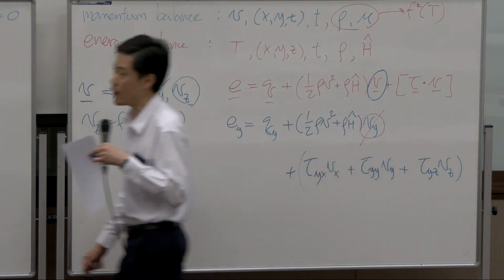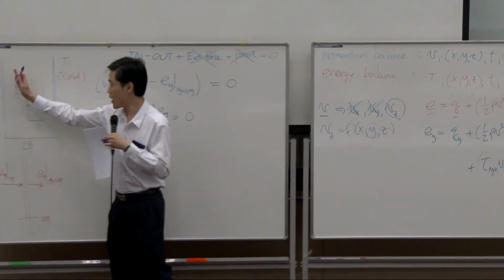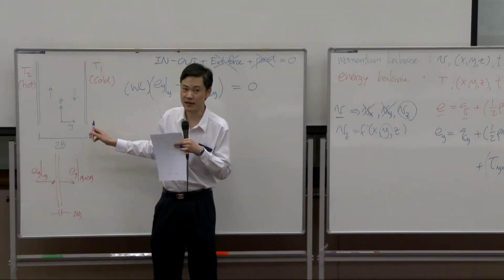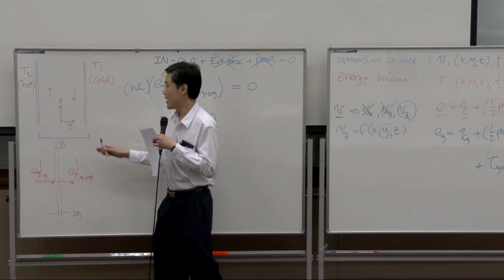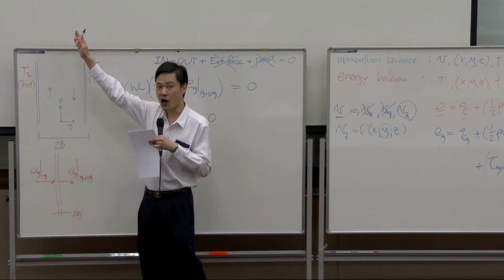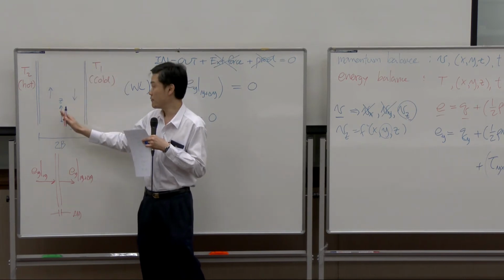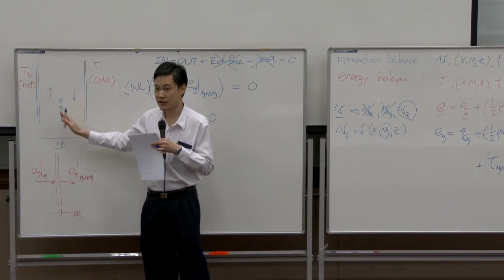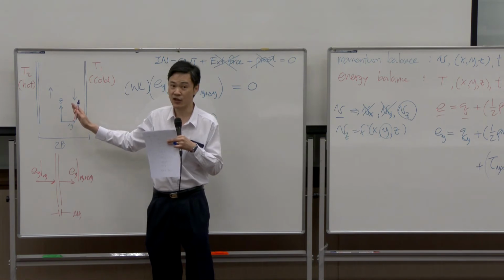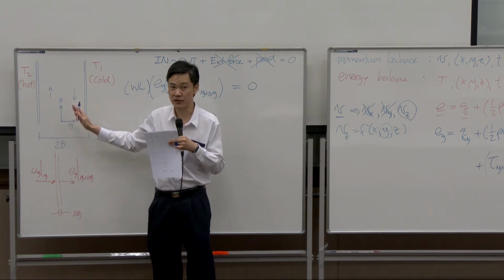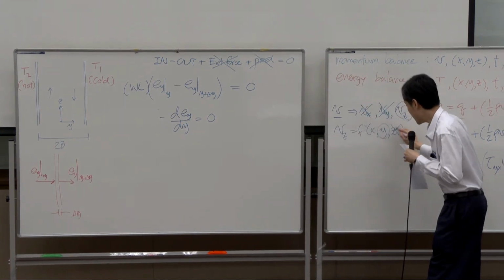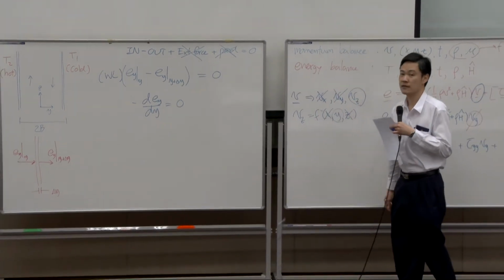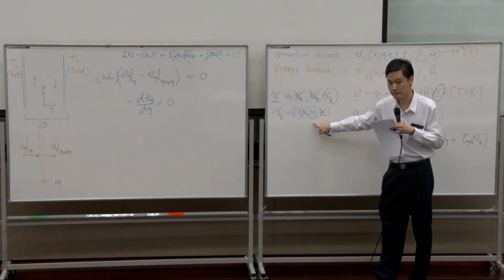You can see that velocity is going up on one side, going down on the other side, so it varies with respect to y. And as I said, the system is really long. Velocity in z direction is supposed to be constant, does not change, there's no acceleration. So in this case, it's not function of z, it's not function of x, it's a function of y only.